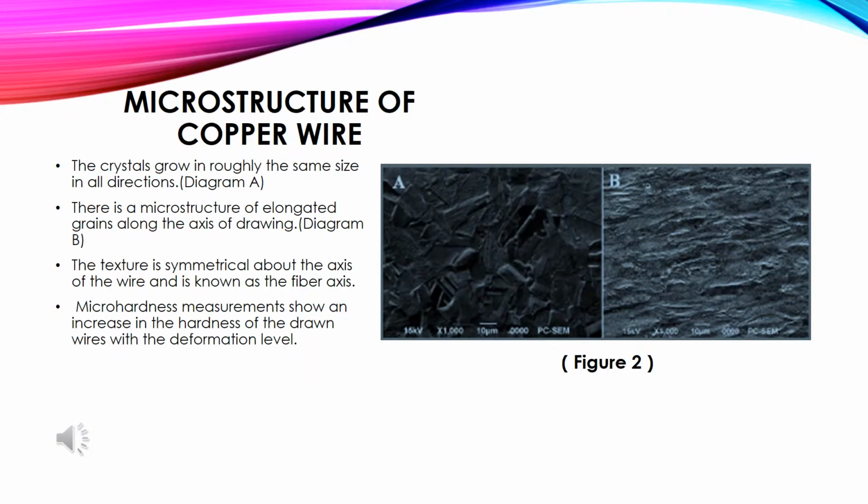Next, we will explain about the microstructure of copper wire and its development. To begin, pure copper or high copper alloys are made from copper ores that are obtained from the mines as sulfides, which contain zinc, lead, and other sulfur. The ores are crushed and milled until they become a powder. A technique known as flotation separates the metal from the non-metal components of the powder. The next step is a concentrating stage where minerals are concentrated into slurry that is about 15% copper. The copper is then melted and purified in several stages until it is 99% pure copper. At this point, it is cast into anodes.